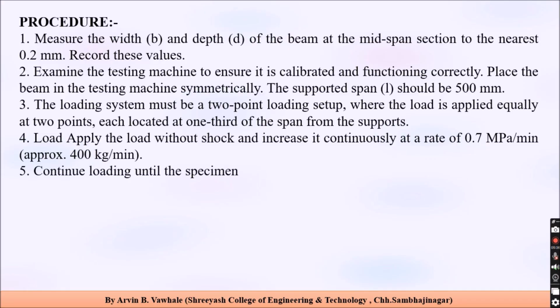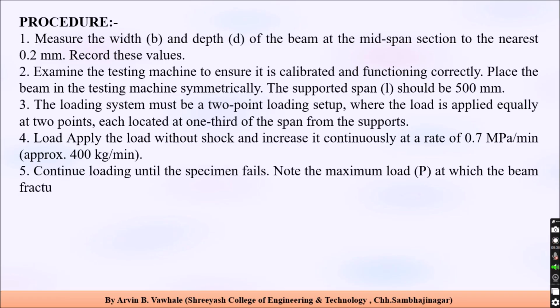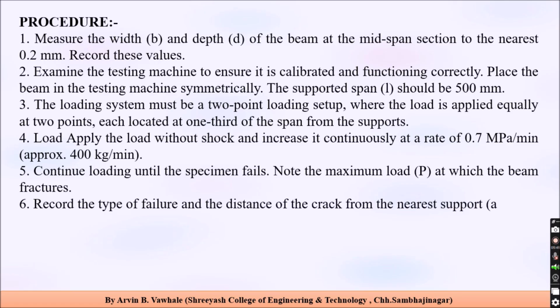5. Continue loading until the specimen fails. Note the maximum load, P, at which the beam fractures. 6. Record the type of failure and the distance of the crack from the nearest support, a.